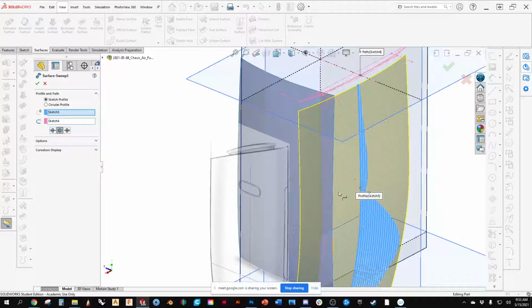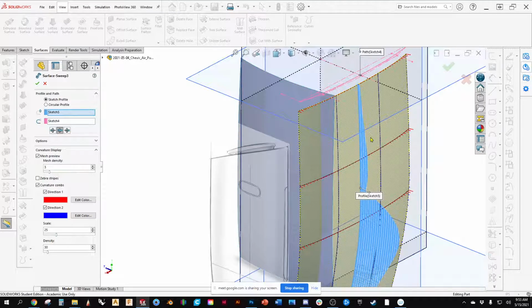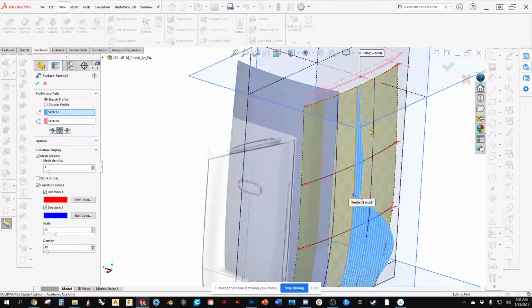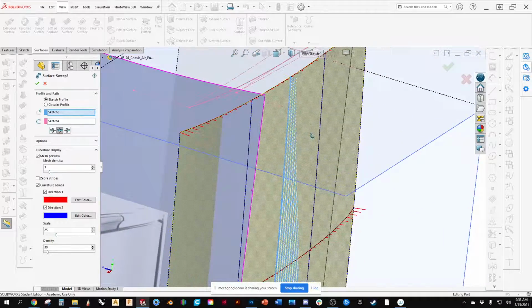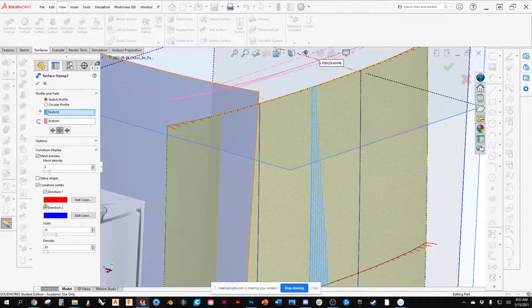We can edit this, and in the edit button or in that surface tool, I can show a curvature comb for that surface going in all the directions. So here is where I'm going to make sure I don't have any wobbles. Just a second way to do it.